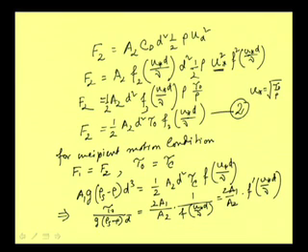So, this critical shear stress divided by g, and then rho s minus rho, basically it is the submerged density we are talking about, that is why it is coming like that, and the diameter of the particle d, and then some constant, and then it is f dash u star d by nu, and this term